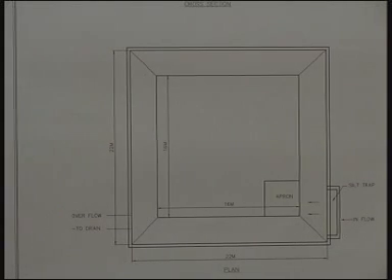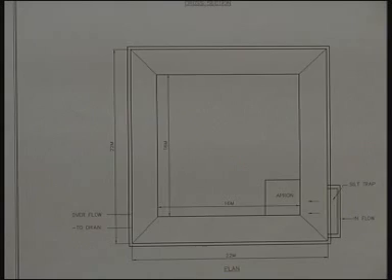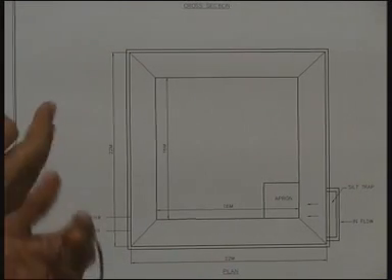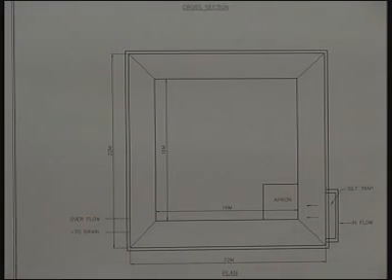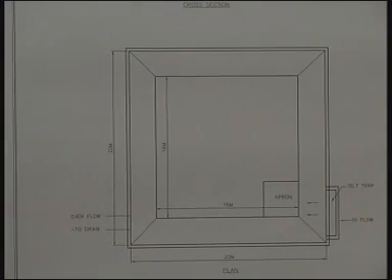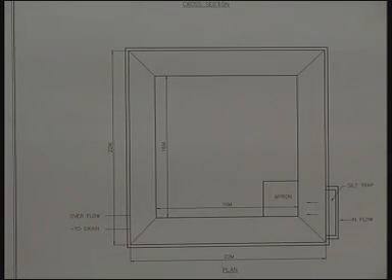When we do all these works, that is the house premises recharge as well as the public places recharge for every 5 hectares, and again a minor irrigation tank down below, then the amount of rainfall that is intercepted and allowed to go for recharge to groundwater would become quite significant.